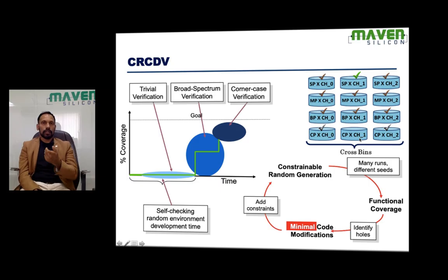So we are going to fix everything, and that would be very similar to a directed test case. We generate a corrupt packet, we make the address for channel 1. So when you send this packet, automatically it has to come out of channel 1. It's called a directed test case. So you generate that particular combination and reach 100% coverage. The coverage closure will always happen through a directed test case.